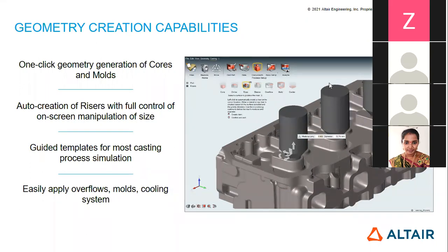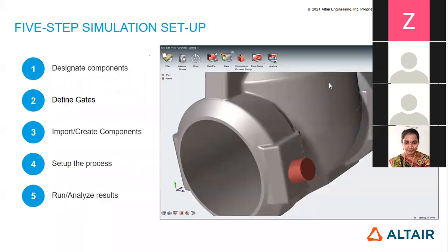Is my design working properly or not? Suppose you have created the die, but your component is not filling properly. It is getting non-filling. Half the portion is filling and half the portion is not filling. Then what would we do? Because a lot of time and money have already been wasted. So at least we have to check these designs at the designing stage.